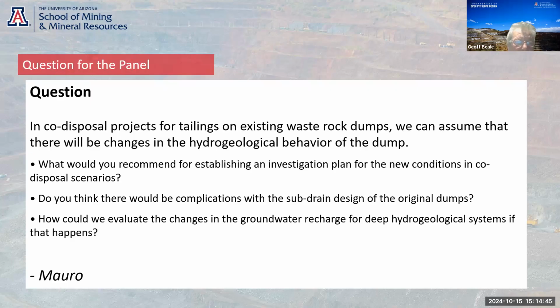So that's an issue, and it needs to be thought through as well. So it's really figuring out what your pore pressures are, what they will be, and trying to do an early estimate of how much water may release from the tailings and where it may go.